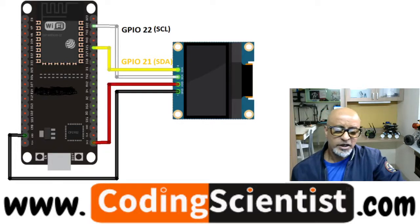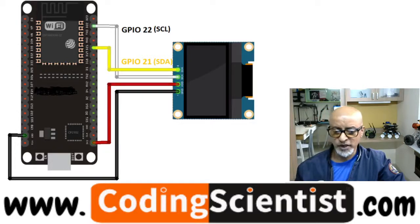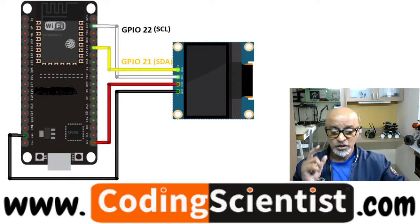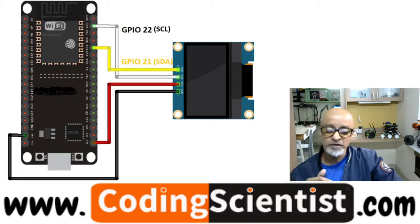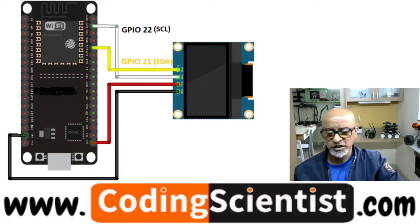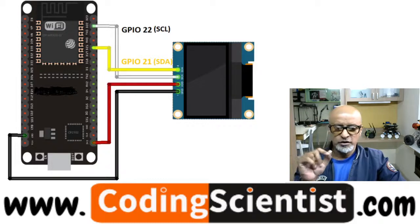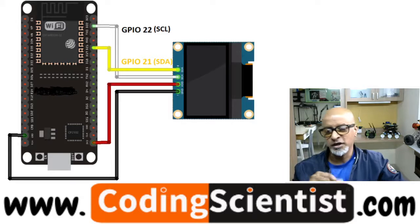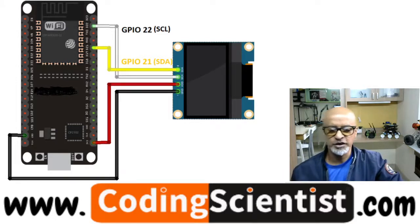What exactly is an OLED, guys? In this particular example, as you know, we are using the I2C communication protocol, and the most suitable pins for I2C communication on the ESP32 are GPIO 22, which is the SCL pin, and GPIO 21, which is the SDA pin. If you look at the circuit drawing here, just follow along the same circuit. Connect your OLED pins to the appropriate GPIO pins 22 and 21, which are your SCL and SDA, and then the ground pin and the VCC, which is your 3.3 volt pin, right?